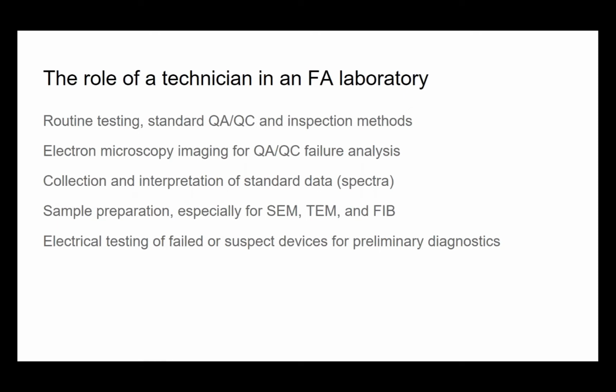They'll collect and interpret standard data spectra from surface analysis. They'll do a lot of sample preparation, especially for electron microscopy, TEM, and FIB, and become proficient in electrical testing of failed or suspect devices and doing the preliminary diagnostics.